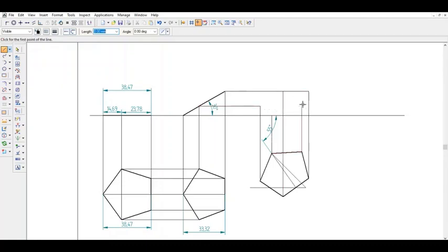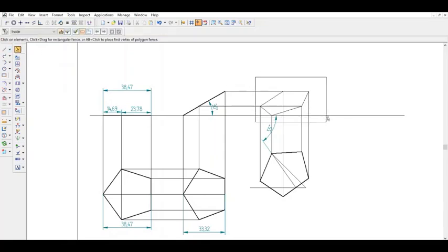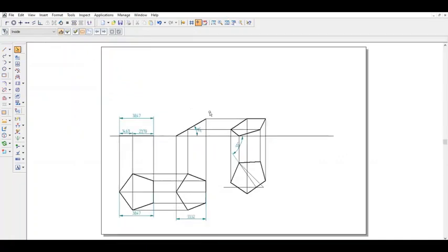Even if you don't join this, generally whenever you are required to show this projection line, you have to show that. Now join all the 5 points starting from the corner. 1, 2, 3. Already we have joined it here, but it doesn't matter, you can join it again. Join all the 5 points, you will get the pentagon. Select the whole thing. Now here you can see that this also is selected, just remove that, change it to 0.5. So that is your problem based on beta angle.